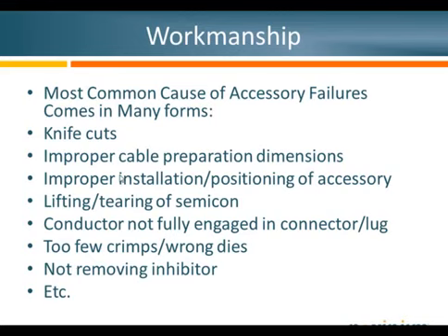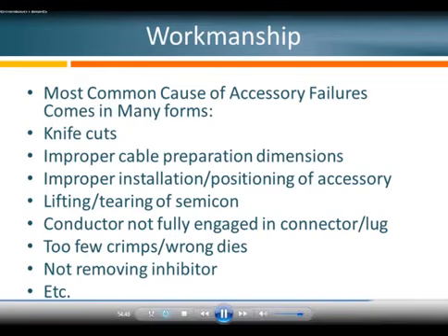And these are just some of the issues that can occur. Knife cuts in the installation, which we talked about, those are bad. If you remove the wrong amount of Semicon, prep the cable incorrectly, remove too much jacket, don't have enough neutral wire to go across, or you improperly position the accessory, or you improperly install it. If you're doing cold shrink, once it's locked down onto the cable, if you push it forward or you stretch it back, you can misposition it that way.